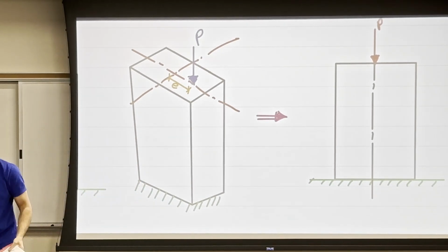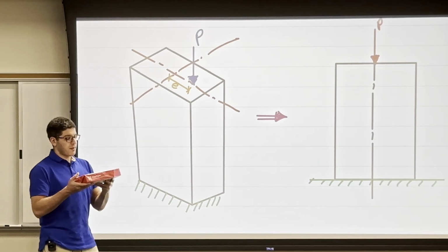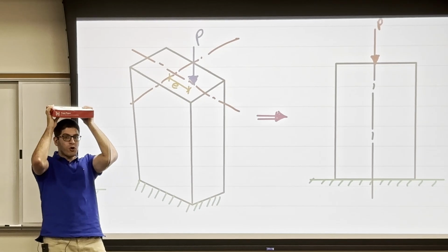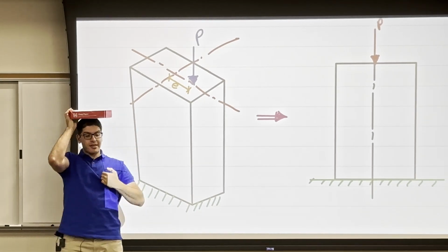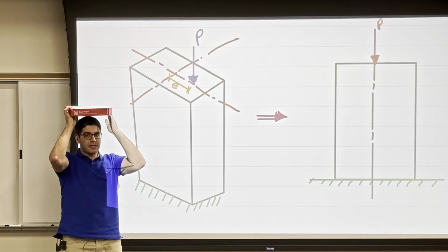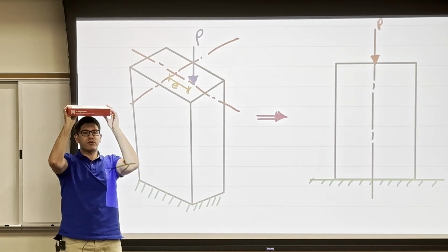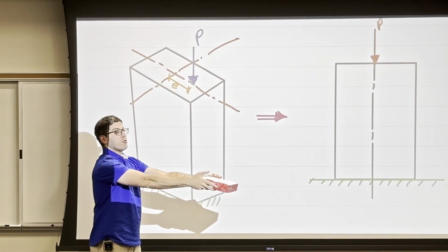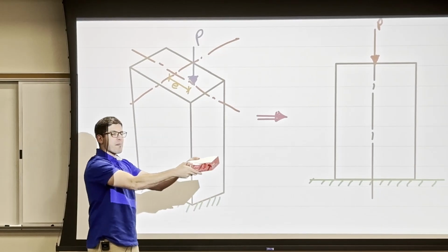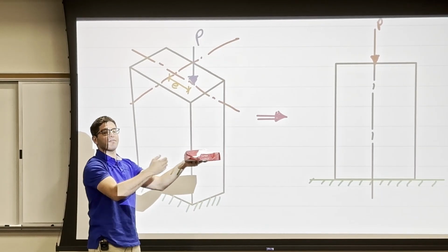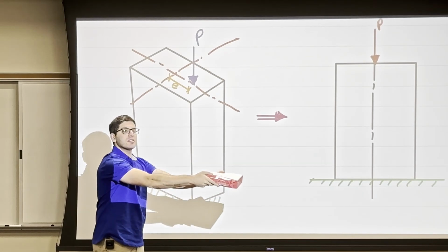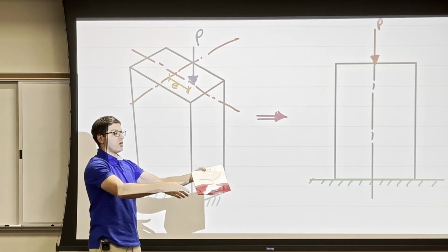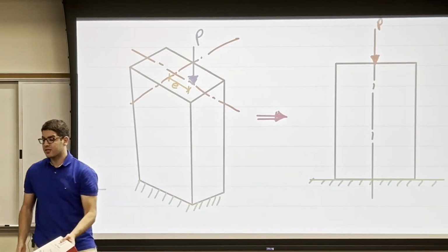Let me explain it in another way. If I do have this large number of papers here, and I just put it here, I'm holding this paper at the longitudinal axis of my body, or like at the core of my body. So my body here feels the P, or the weight of the paper. But if I put the paper that way, away from myself, look, my body is bending that way. My core still feels the weight of the paper, in addition to this, the bending moment, which is the weight of the paper multiplied by that distance to my core. So this bending moment is what we're going to consider here.